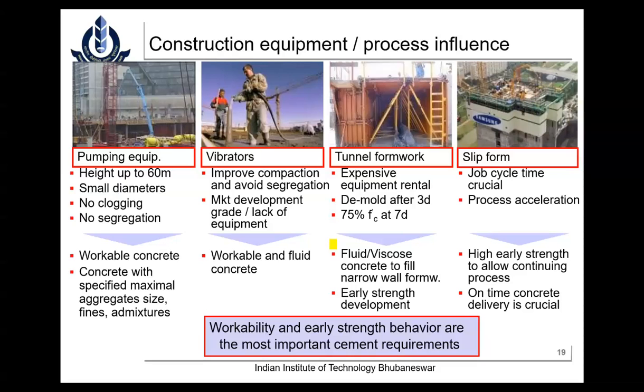Can I interrupt here, sir, for a moment? Yeah, please. When you were talking about cement-admixture compatibility, as you rightly pointed out, there is always a challenge at the site level when we bring cement and admixture together. So before the admixture is used in the project, we take that admixture and cement, make the specified concrete mix at our Ramco Research and Development Center itself, and see whether it is compatible or not. If it is not compatible, we coordinate with the admixture personnel and look at how it can be resolved. That is one kind of support we give to construction professionals. That's a very good point you have raised.